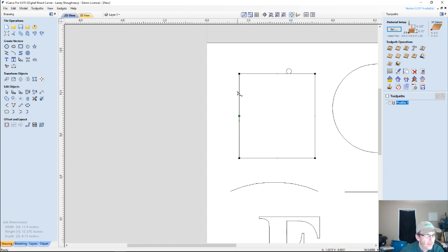So not only am I going to get witness lines all the way around, but I'm going to get this nice little half router bit, or a small curve cut, in my board. I don't want that right in the middle, or right on the side where it's visible. If I have the opportunity on any project, I want it somewhere that is out of the way. So I definitely want a corner to be a start point versus the middle of the field, if I have one.